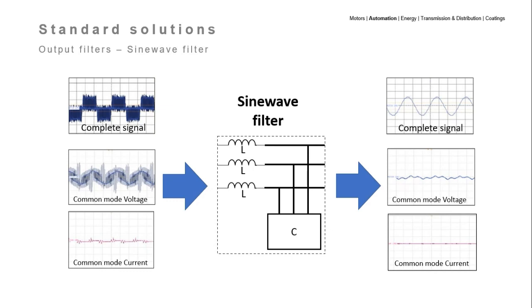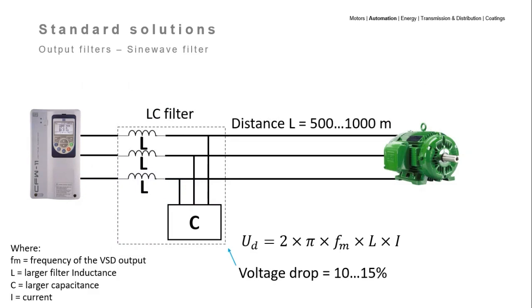On the other hand, the cost of its implementation is higher compared to DVDT. In this way, its ability to reduce voltage peaks and noise in the network is greater, allowing the distance between the VSD and the electric motor to be greater than previous filters. Just like any other filter for the protection of electric motors, the sine wave filter is installed at the output of the VSD. This results in an even cleaner sinusoidal when compared with the DVDT filter.